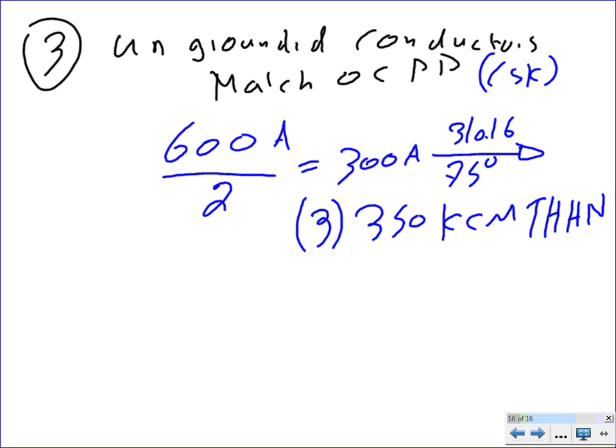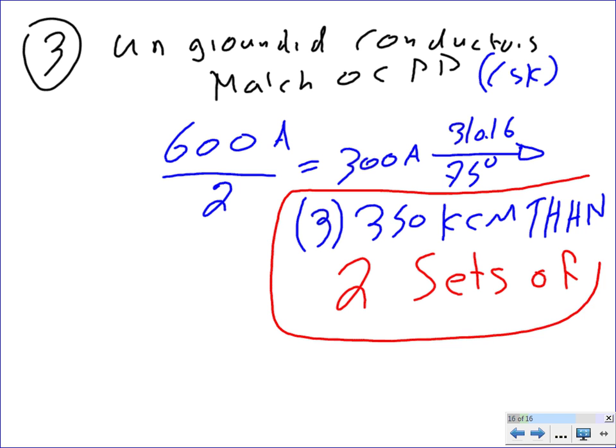Okay. How many sets? 2 sets of 3 conductors, each one of them 500 kcm, insulation THHN. Here are my conductors, so please read bottom to top. Why THHN? Most likely, guys, if you have a receptacle panel, it's going to be inside. Not most likely, 99% of the time, it's going to be THHN, or THHN/THW, one insulation.